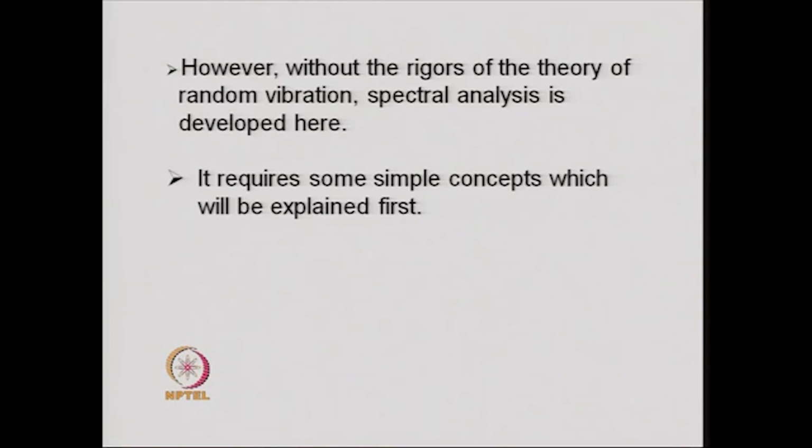Since the input is a random process, they also would constitute random processes. So, the concept of power spectral density function not only of the earthquake ground motion, but also the power spectral density function of displacement, of acceleration, of bending moments, must be well understood.